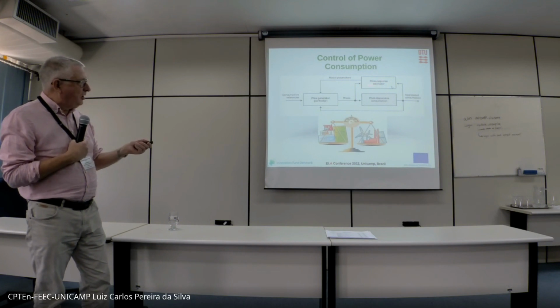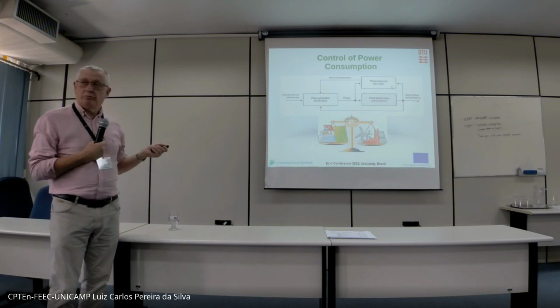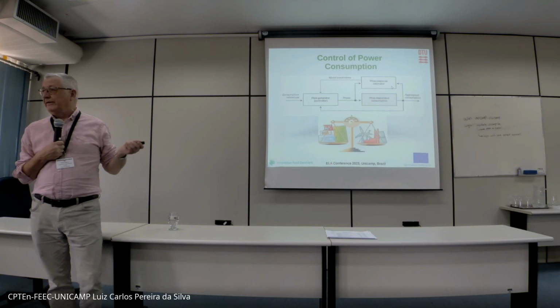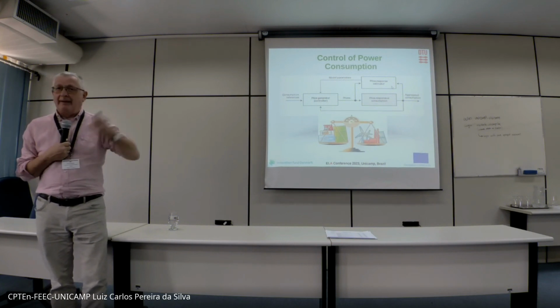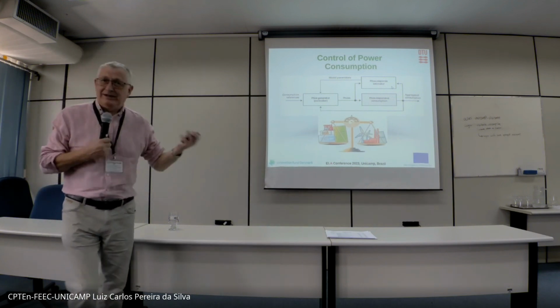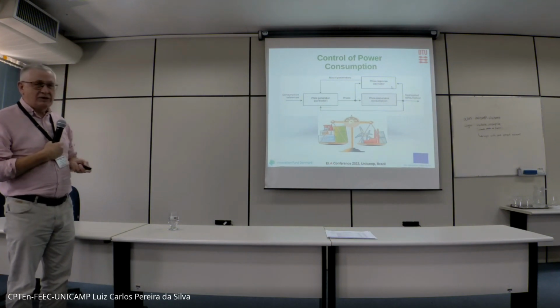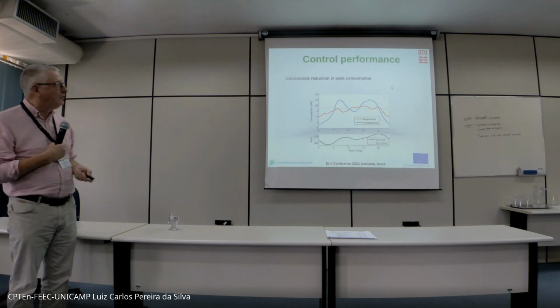And if you have this model, then you can also derive a controller, so you send the price which can control the load. We also have a course on stochastic control theory, and this is maybe exercise number 3. If you have an Armax model, how then to design the controller so you control the load. So basically, rather basic stuff, I would say. This is the total setting for controlling the peak load, and this is what we achieved in that case: we removed the morning peak and the afternoon peak.